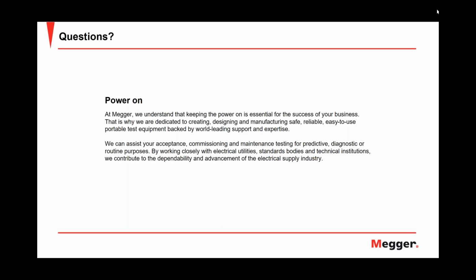The DC source has one other effect on a breakdown test, because a breakdown test means I have a fault, so I have somewhere an air gap in the medium voltage cable. When you apply DC, you always have this additional effect of ionization of the air. As you keep the DC voltage on, the air starts to ionize, and then the air breaks down earlier at a lower voltage and flashes over. So the fault locating application for DC is very different from the test functionality.